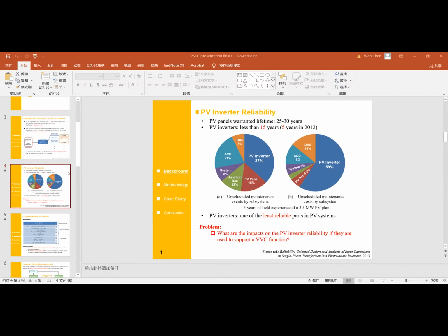I think the second has a second question. The second question is related to the lifespan, the life of the PV systems. So do you have some idea for using reactive power for the life? Yes. Why do solar PV inverters have less lifetime? Because the active power from the PV panels is really irregularly varying. It's fluctuant, right? And this is a key parameter for the inverter lifetime. So the reactive power can be used to mitigate this fluctuation. So that's the point.